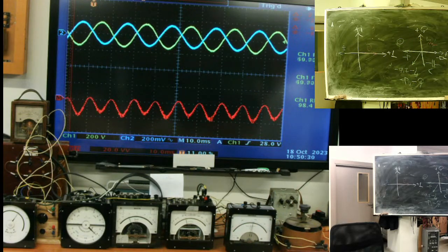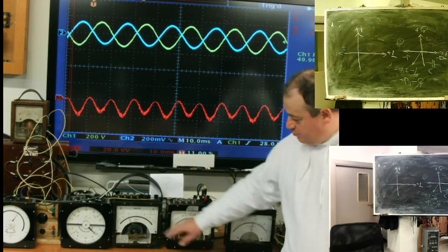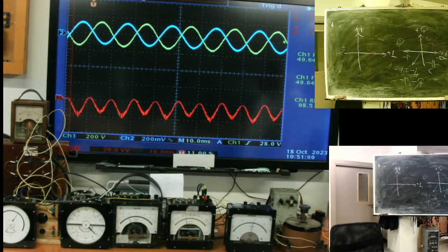And the machine becomes a kind of huge capacitor. Overexcited synchronous machine supplies reactive power to the network. It's the way to control a network's voltage. If you overexcite your generator, voltage will rise. You see it as a flow of reactive power to the network. Now you see the mode when the machine supplies both active and reactive power to the network.